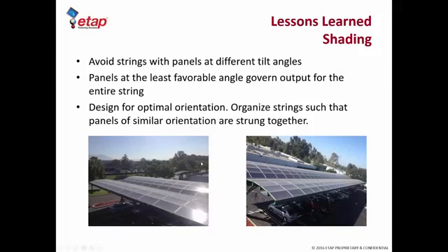If you recall, when I put in an actual irradiance of 642 watts per meter squared, we're assuming that all the panels are facing the sun appropriately, or they're being tracked in such a manner that the tilt angles are optimal. But as we can see here, the tilt angles are not optimal, and that really accounts for the difference in the model versus the real-time measured value.